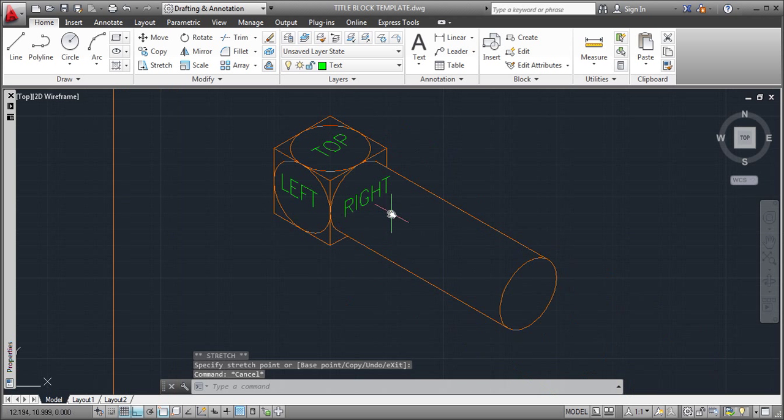Now if you look at the piping, all it pretty much is lines and also boxes and cylinders, so you should have all the information you need. As you're doing the valves, just to give you a little bit of help, if you go ahead and click the line command, you have your ortho on. Find the plane that you would like to use, F5.